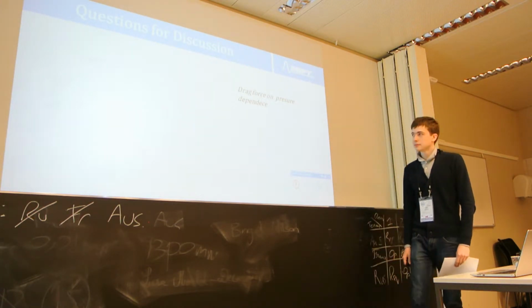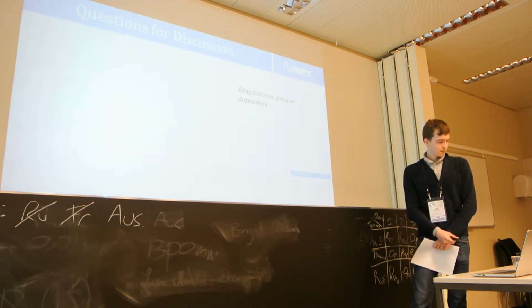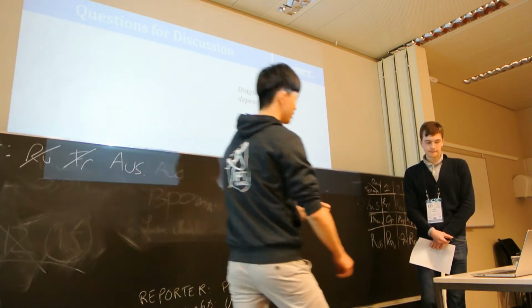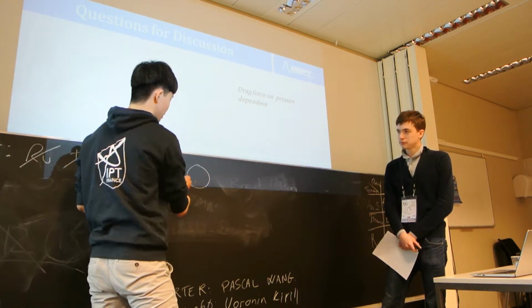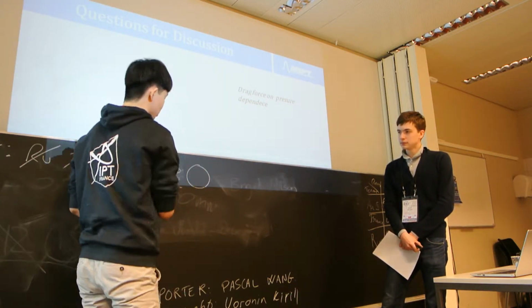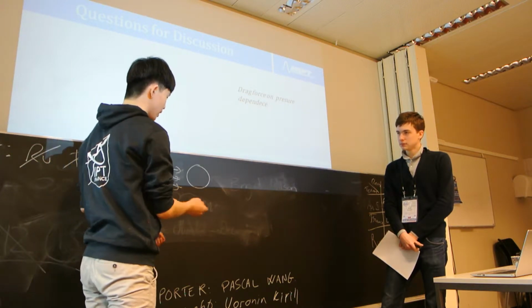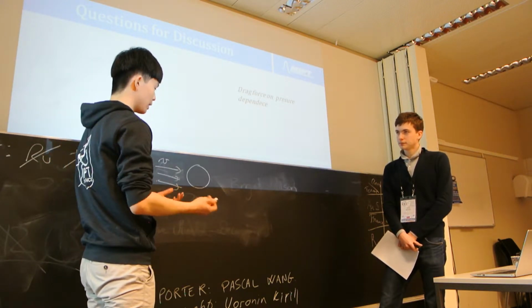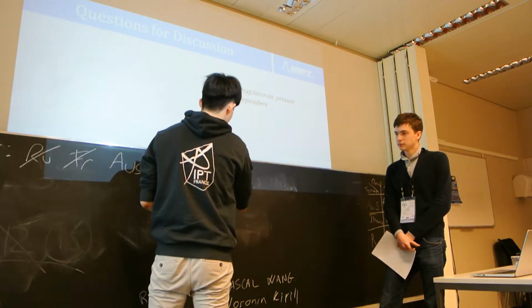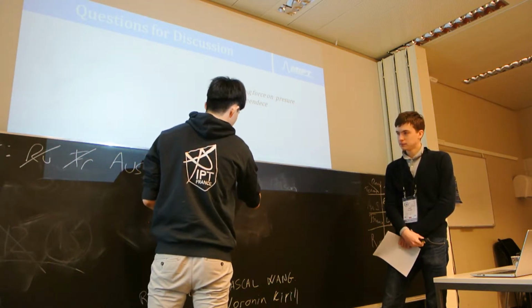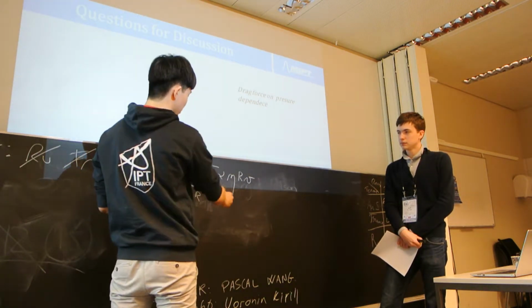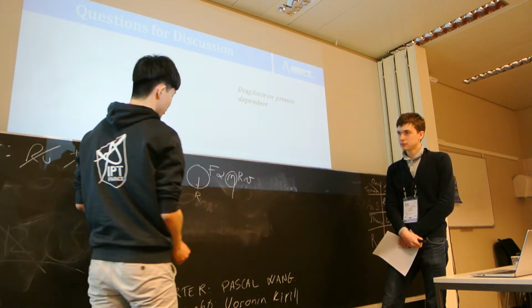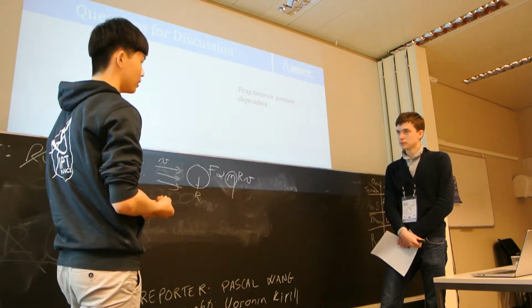So thank you for your remarks. I'd like to address first the question that you mentioned here. How does the drag force depend on pressure? You have different expressions of the drag force depending on the Reynolds number. For example, if you consider a sphere with a relative wind blowing at velocity v, at low Reynolds number, it's common to approximate the drag force as proportional to v. You put a radius of the ball for the geometric function, but the important part here is the viscosity of the fluid, and it depends on the pressure.